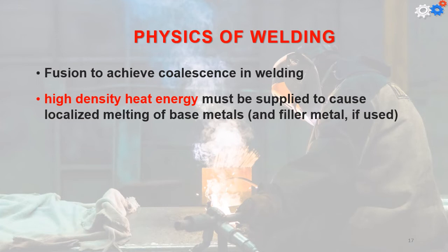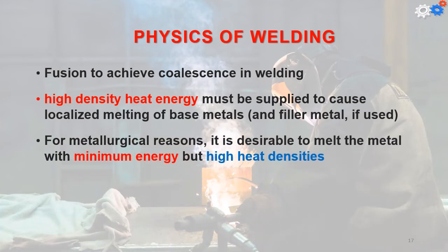Fusion is used to achieve coalescence in welding. So high density heat energy must be supplied to cause localized melting of the base metals and the filler metals if used. For metallurgical reasons, it is desirable to melt the metal with minimum energy but high heat densities.